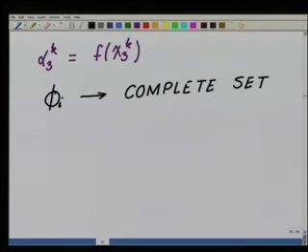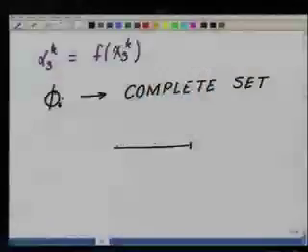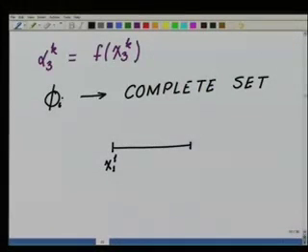So in the construction of these phi i's, one has to be very careful. One cannot arbitrarily define the function phi i as we wish. Another point to note is that the point x2 of k that we have taken, we have said it is at the mid side. It need not be, it could be anywhere, but as a convention, it is taken at the middle of the element. But one should remember, it need not be the case, especially when we have curved elements, which we will be dealing with later on.